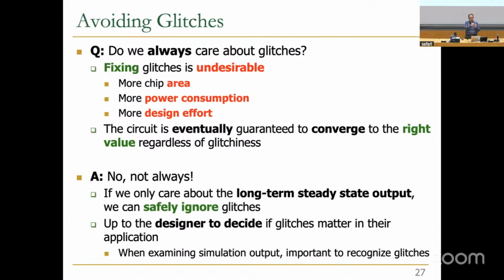So one simple glitch can propagate to many other circuits, which can consume a lot of power. That's why when we design sequential circuits, we usually prefer Moore machines, as long as they don't need a lot more states compared to Mealy. And they work very well for glitches, for example.